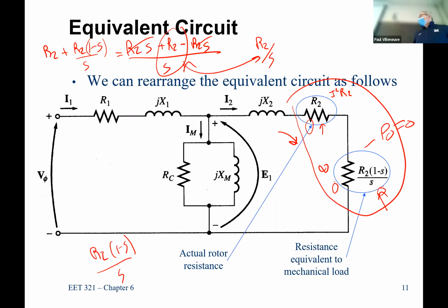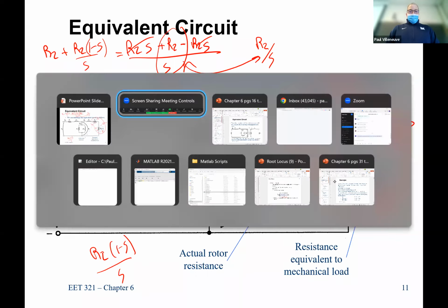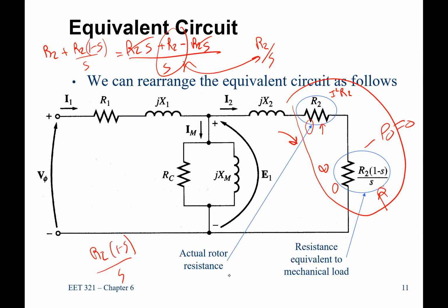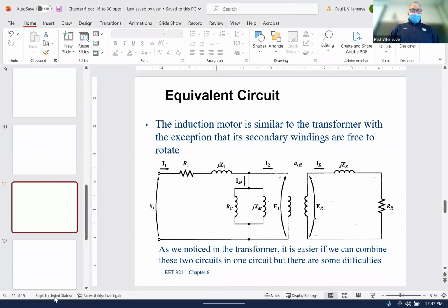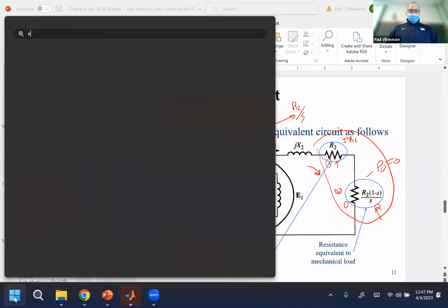Now, do you remember how I said last class, we looked at some nameplate stuff? If you have a 4-pole machine, what's a typical operating speed when it puts out regular power, not maximum? Very close to 1800, right? Something like 1785, which is what my motors are. Yeah, 1785. Let's look at some nameplates here.